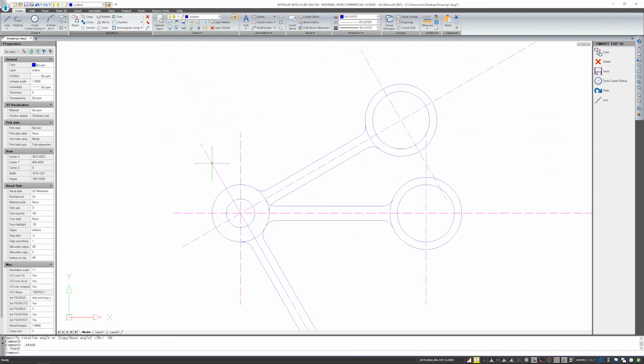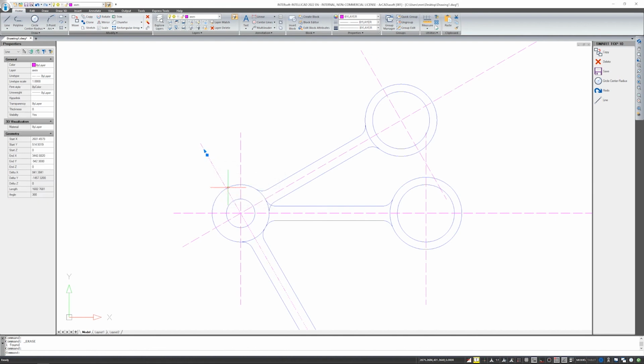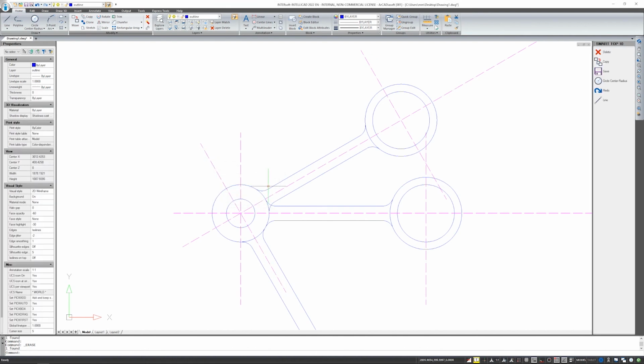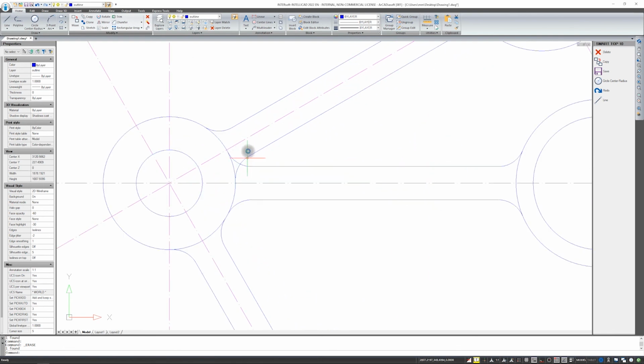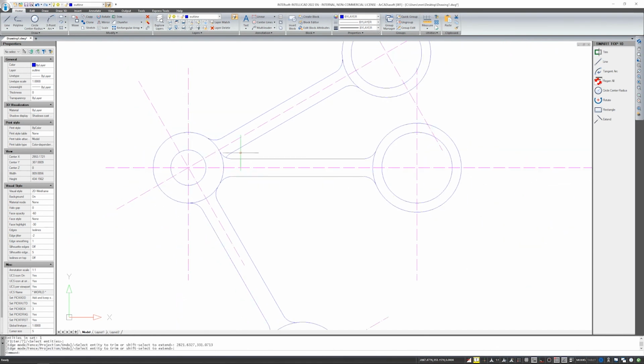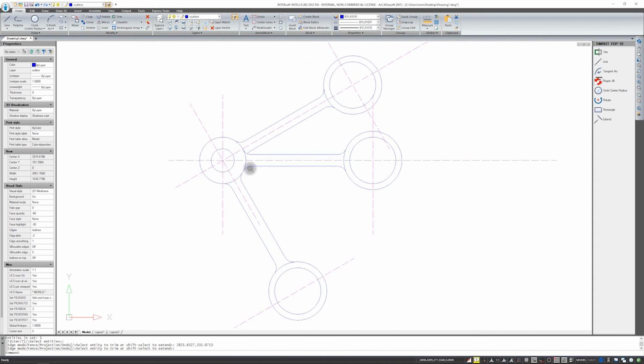These elements overlap. I could use the overkill option for this, but I'm only going to remove this one element at this point to make it okay. Here these elements overlap. One is higher, the other one is lower. So select the cutting element and then the one that is hiding below it. If this element was to be duplicated several times at the same distances, I could use the array option. I'll show the array in another example.